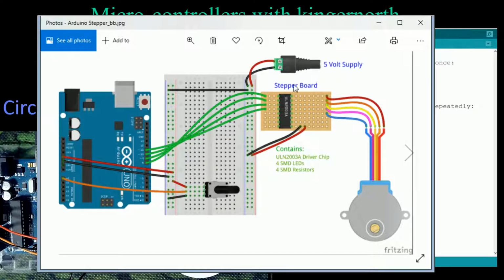So what we're doing in here is we're going to be looking at these. Here's my connector here with my 5 volts coming in from outside. It comes down here and connects back to the board. This will then use the power on this side of it. So everything to the right of the chip will actually use the power from external. Everything to the left of the chip will use the power in here. And actually it's just the common lead that is connected together on the 2 power supplies, one from the Uno and one from the external. Always connect the grounds together to give you that common path, because when we put power to these pins, we need it to get back to the Uno somehow. So that's really what's involved here.